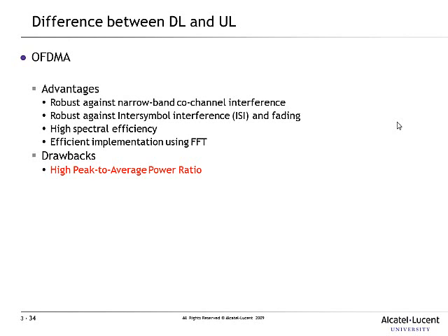We've also seen how we have overcome the effect of intersymbol interference by the use of cyclic prefix, and the fact that we are overlapping spectra of various signals means we have high spectral efficiency. Okay, and we've now been able to efficiently implement the FFT processes so that it's available to the man on the street.